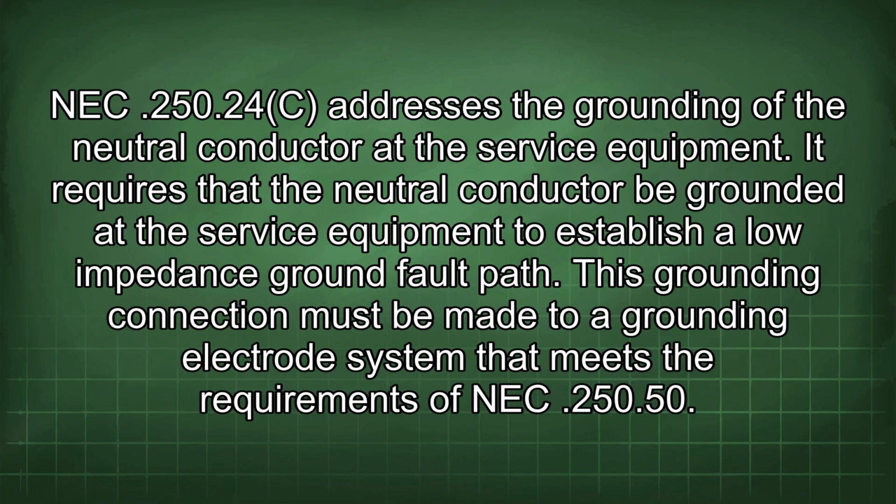NEC 250.24(C) addresses the grounding of the neutral conductor at the service equipment. It requires that the neutral conductor be grounded at the service equipment to establish a low impedance ground fault path. This grounding connection must be made to a grounding electrode system that meets the requirements of NEC 250.50.